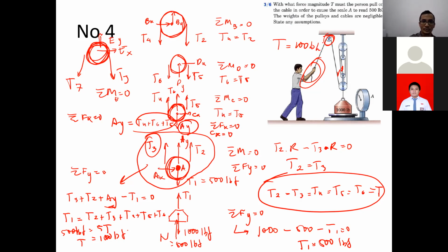So this is the way to draw the free body diagram, so it will interconnect to each other. I believe it answers one of the questions of your friend just now, William, if I'm not mistaken, right, William? If we draw it, we don't have to draw the tension or the rope, but we draw the force due to the tension, the force due to the rope. So we can draw the free body diagram so it will interconnect to each other like this, action and reaction.